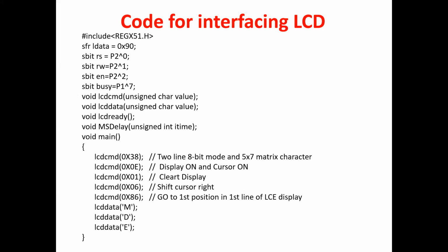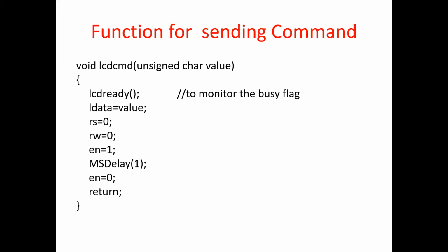LCD data D means letter D will be displayed. Data means the data which we are sending is for display. Okay, now we'll see what these commands are: LCD command, LCD CMD, LCD data. What are these functions?